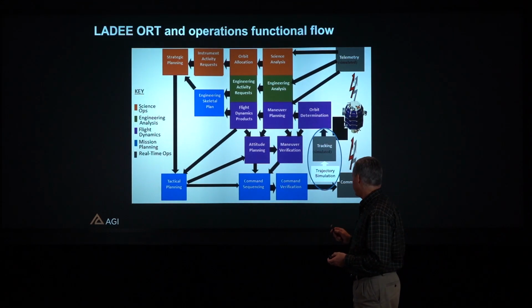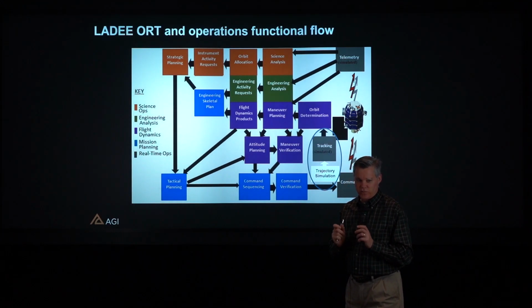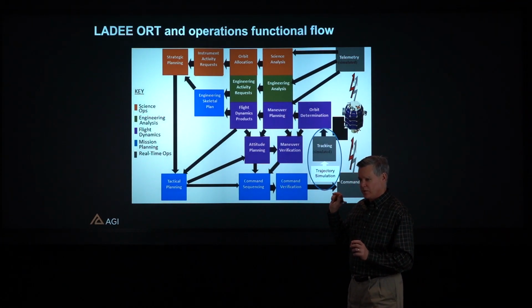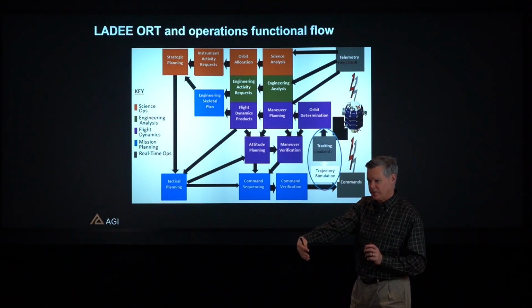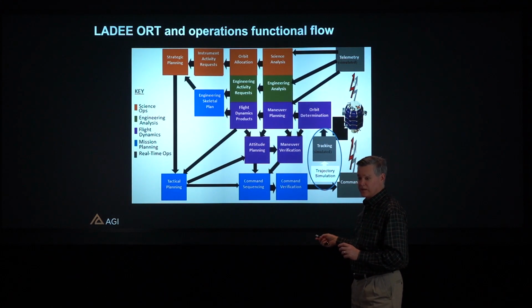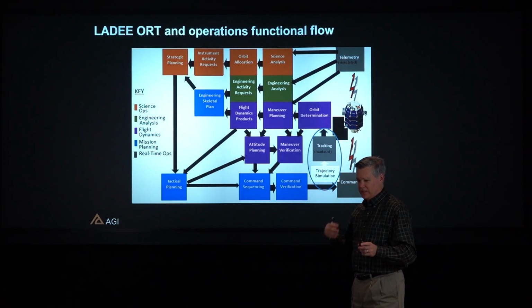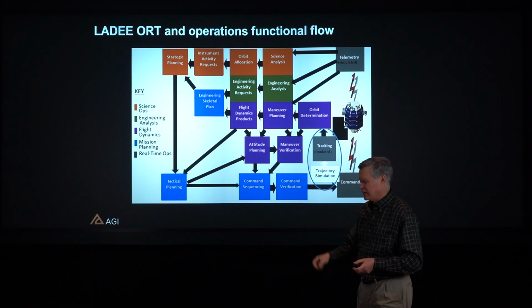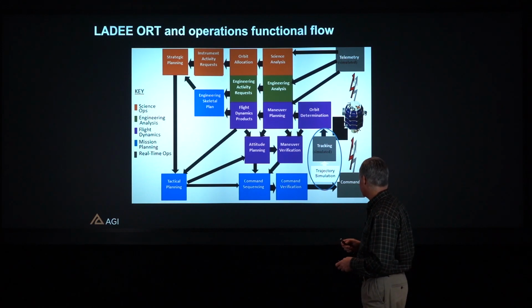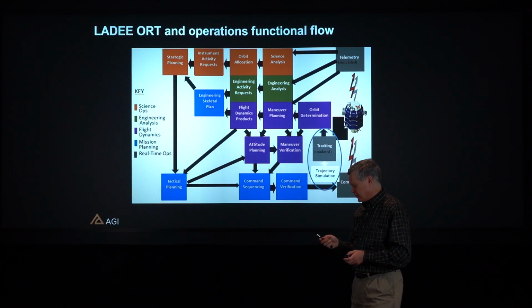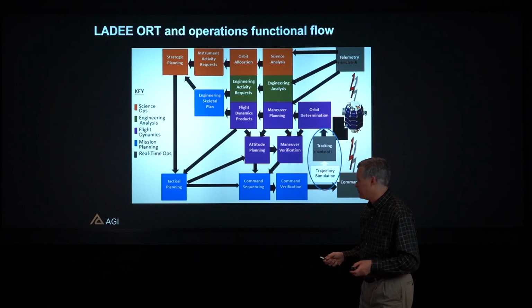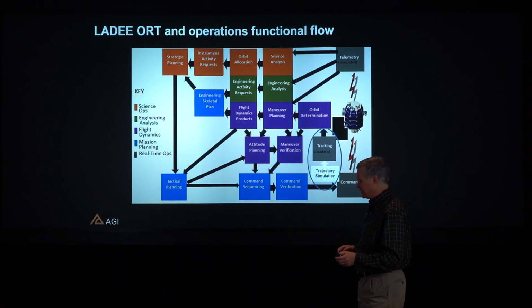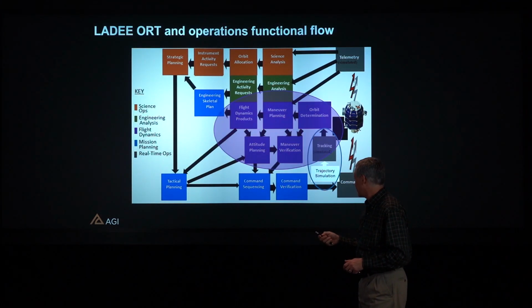So the important point there was that we were using the same truth trajectory that we generated for the simulation to drive both the creation of observational data and to go through the spacecraft simulator, so that when simulated telemetry was produced, the simulated telemetry agreed with what we produced in the tracking data. Right? So once again, we're not trying to trick operators by doing something that's impossible. We want to keep things consistent and allow them to attack the anomalies that we want them to see.